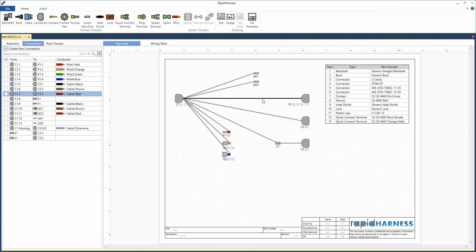So what I'll do is right click on this first one and select Add Branch Point, and then I'll do the same thing to the second one here. And now you can see I have these circles here which I can drag around, and if I drop them on top of each other, then these two branch points become one, and these bundles are merged together here. And the shortcut for this is if I select more than one bundle at a time, I can right click and choose Merge Bundles, and here we can see that automatically created a branch point and merged those two bundles together.